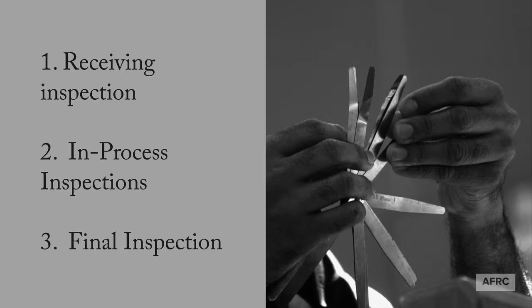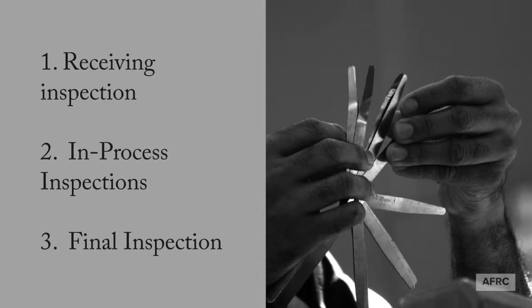Most of us are familiar with in-process inspection and final inspection. And I'd like to talk about in-process inspections for a minute. A lot of times the work instructions that we're using, the drawings, whatever, they don't specify everything you should be looking at. And so if we wait to look at that product in the final inspection stage, we've probably missed some important quality requirements that we should have been looking at while the product was being produced. So I'm going to go over a couple of examples here.